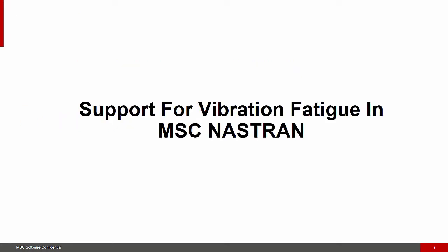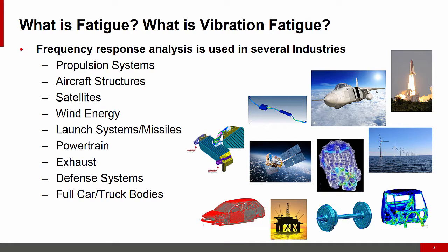Let's start by going into the vibration fatigue capabilities of MSC Nastran and Patran. Before we go into details, I'd like to give a short background on fatigue and vibration fatigue. What is fatigue? Although fatigue can have several definitions, the one that's most common among engineers is failure under a repeated or varying load which will never reach a level sufficient to cause failure in a single application. So in other words, the load, if applied once, will not cause failure in the structure.